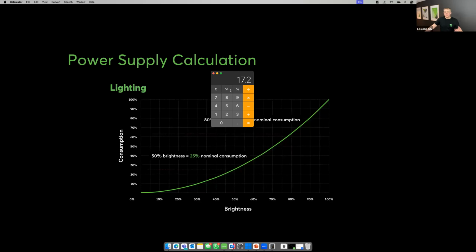The reason being is because with the RGBW dimmer that you're going to be using to control it, you've got red, green, blue, and then white. If you're going to be using the white and you want to make it warmer or cooler, you're going to be mixing in the reds or perhaps the blues. Or if you're choosing a color, the white isn't used at all, and it's just the RGB. So really, your maximum possibility is going to be in the region of 60 watts. So straight away, we've saved 20 watts on that power supply calculation.